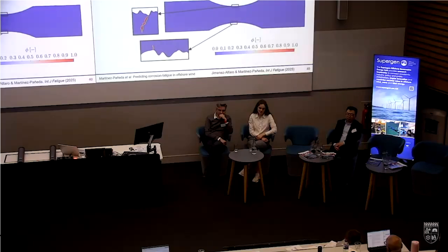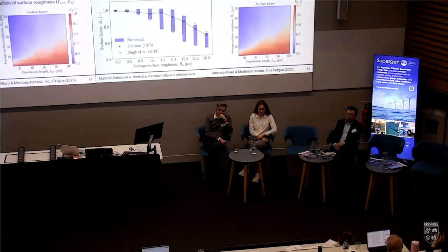So we need to understand this first stage where they were not protected, how this impacted fatigue life. You can do that basically by developing a methodology that allows you to uniquely characterize any surface roughness state as a function of 2 parameters. Then we combine that with those phase field fatigue models that I showed you before. You can see some cracks propagating here, and then we were able to predict failure as a function of surface roughness. The predictions seem to match experiments very well, and we created a map to cover all possible conditions.